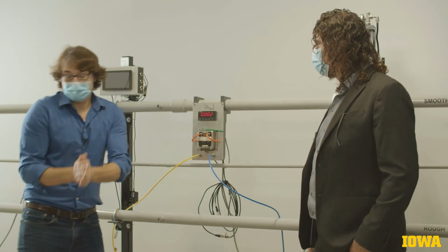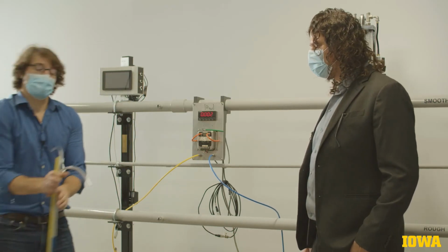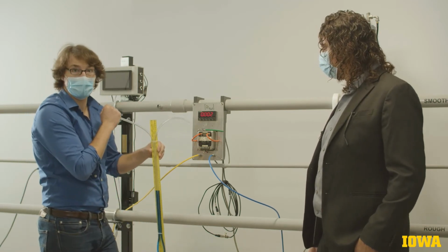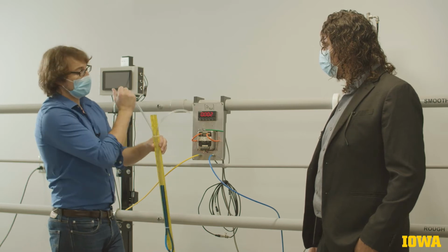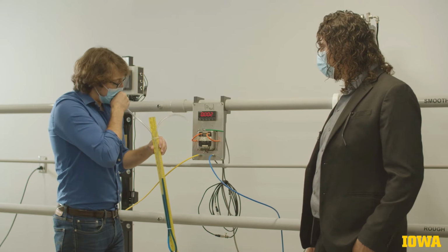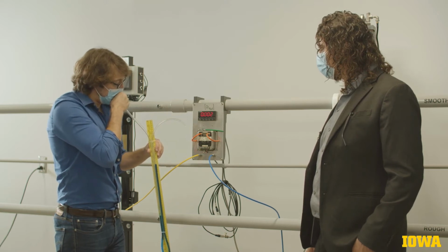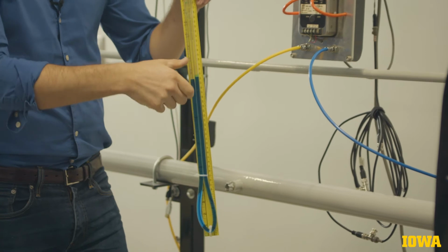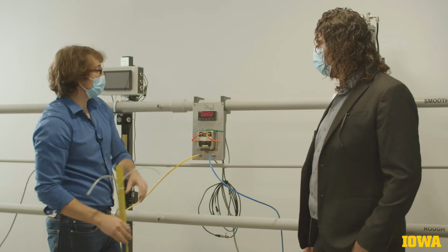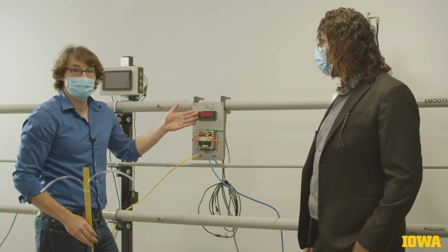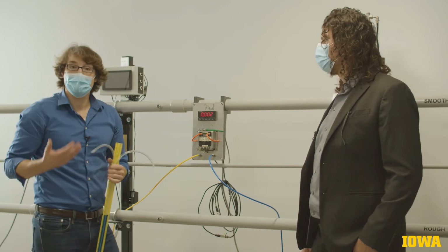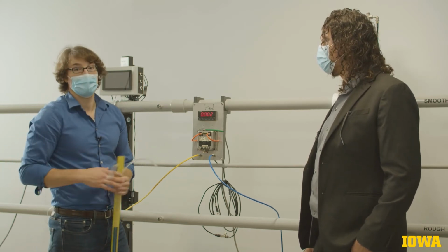If you recall our lessons on manometry, you'll remember that a manometer is a device that allows you to visualize a pressure difference as a water elevation. By increasing the pressure on one leg, you induce a change in the relative water column heights that can be measured in feet, which is precisely what's being read out on this display. So we need to be mindful that the numbers we get from this display have to be converted to true pressures using the principles of hydrostatics.